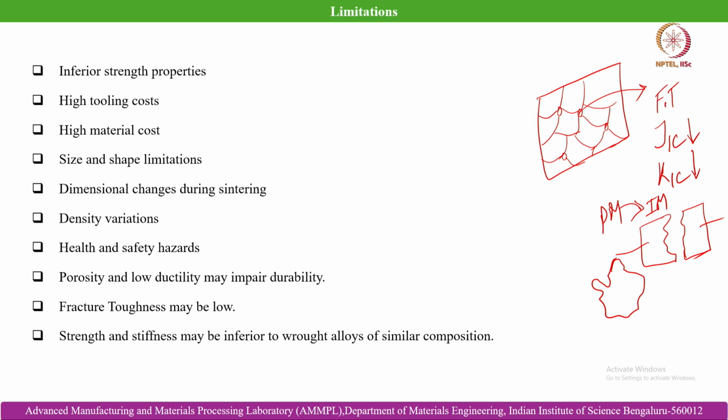So, you can directly machine down the component post development and arrive at the resultant dimensional attributes in the developed parts. Whereas, because powder metallurgy is a net shape process, we have to machine the die cavity in an effective way, with dimensional control, so that it is an exact replica of the dimensions of the end part that you are going to achieve in the sintered part.